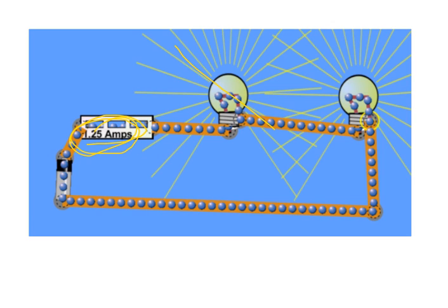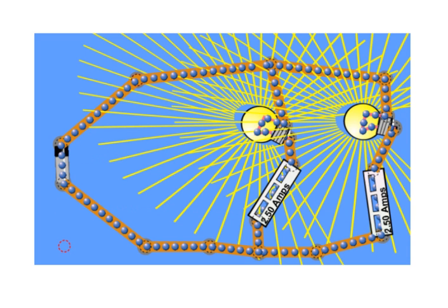This is now what parallel looks like, and you'll notice that if I were to measure the amps, it's actually back up to 2.5 for both, because what happens is these electrons can either go through loop 1 or they can go through loop 2, but the electrons aren't getting slowed down doubly. Okay? Like the electrons that choose to go this way, they only have to run through one device. And so they can still run at 2.5 amps.